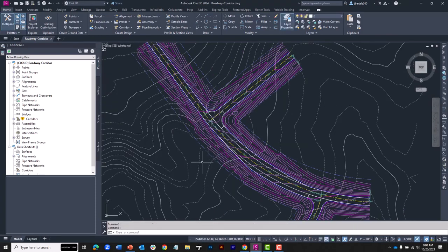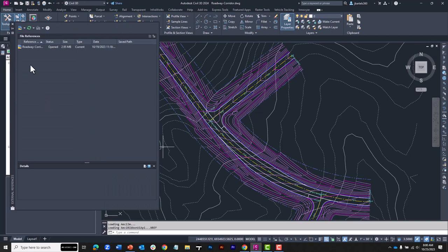As you know, when we open this file, it is locking that file in the cloud. It is also pulling that file and caching it locally to my machine if it needs to. I now have ownership of this drawing. To externally reference files, I am going to type XREF because I'm old-fashioned. And in the External References Manager, I'll right-click and I'll choose Attach DWG.